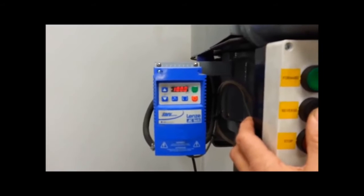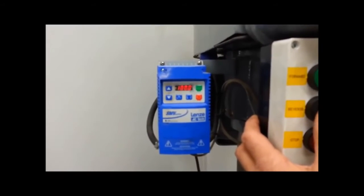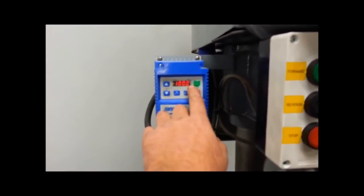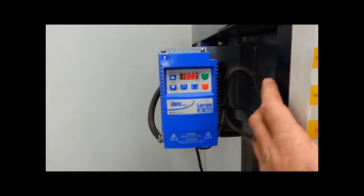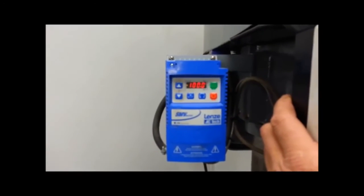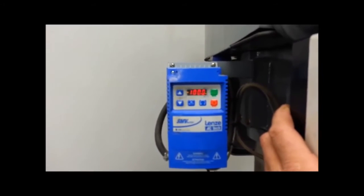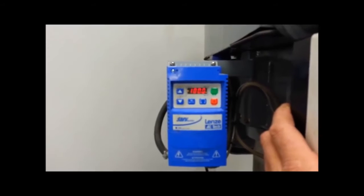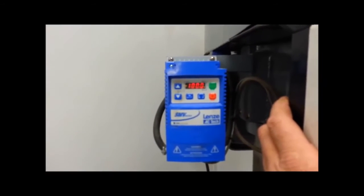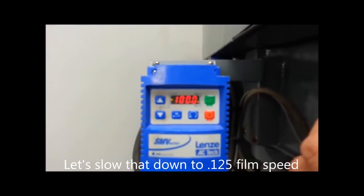So it's actually applying an electrical brake to the motor, and you'll see a reverse command right here get applied, and it'll just be blinking until the reverse command gets taken. It happens in the blink of an eye, but it decelerated the motor and applied the reverse command after the motor had come to a complete stop and the braking was finished. And we go back to forward and let you watch that one more time.